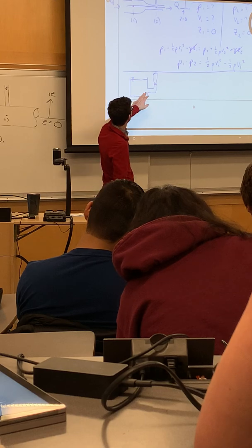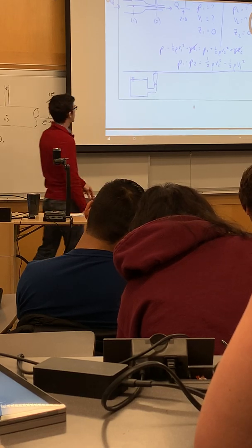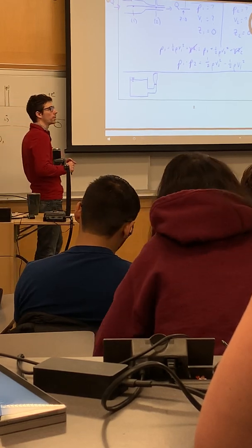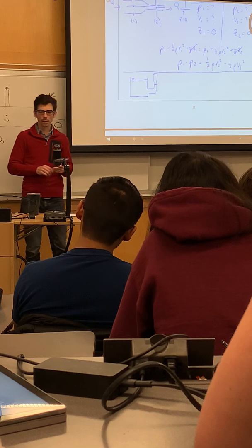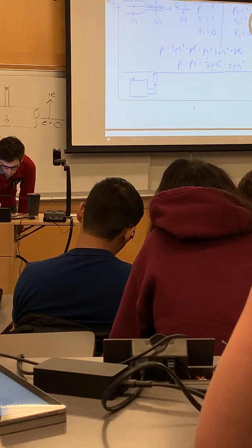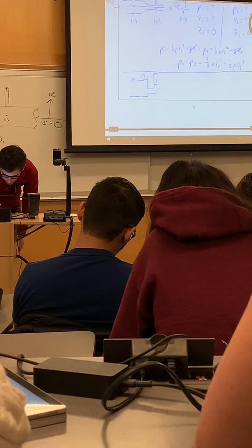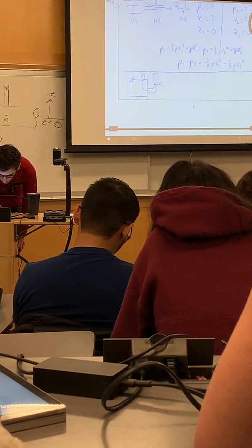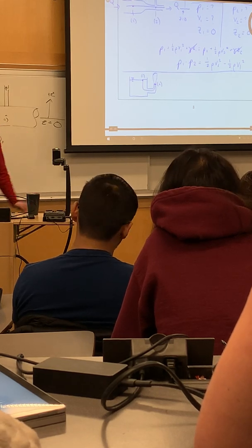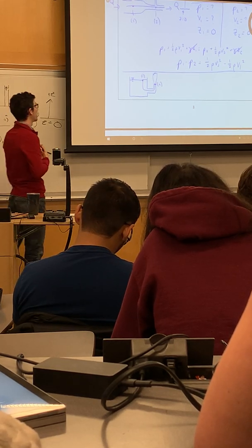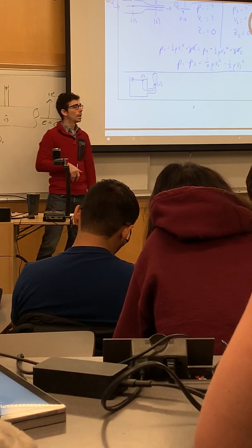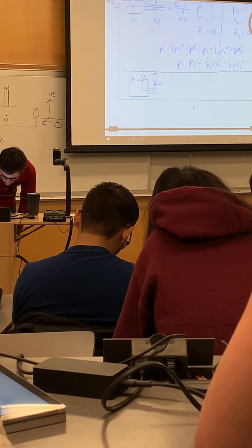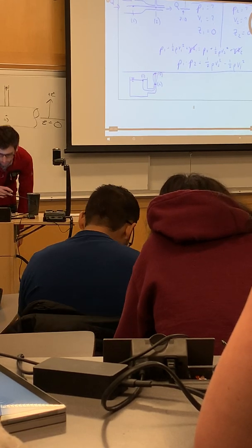We can analyze this situation with the Bernoulli equation, but this is an example of where it's useful to break it into pieces. In this example, we could do just as we did before: apply Bernoulli on a streamline from 1 to 2. And we end up with the same equation as we showed previously. But we can also extend this, and evaluate a streamline along the unconfined flow from 2 to 3.